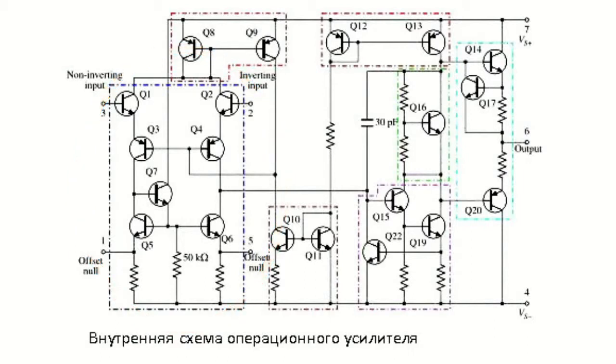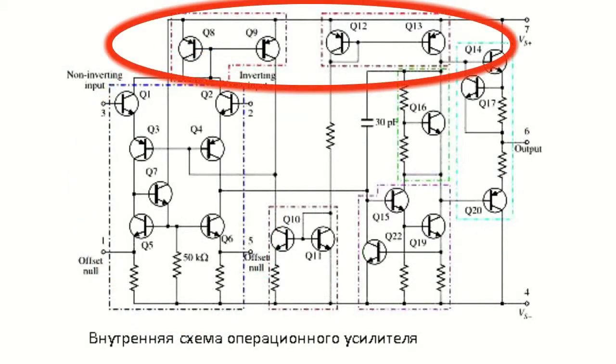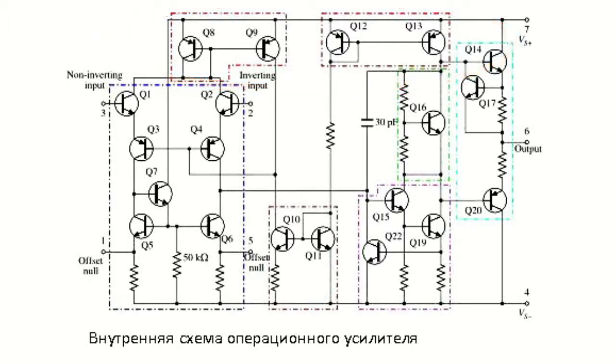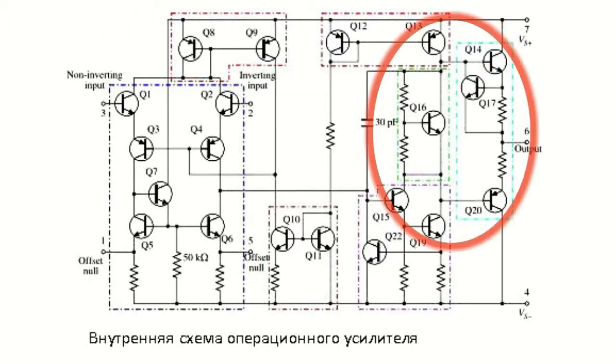Voltage amplifier has a high voltage gain factor. Amplitude frequency characteristic drop is similar to that of a unipolar low-pass filter. It usually has a single output. Output amplifier provides a high current output capacity, low output resistance, the limiting of output current and short-circuit protection.